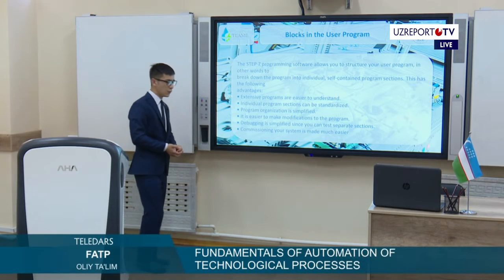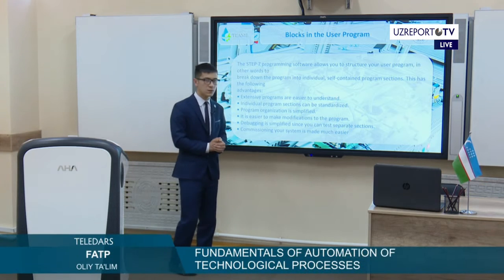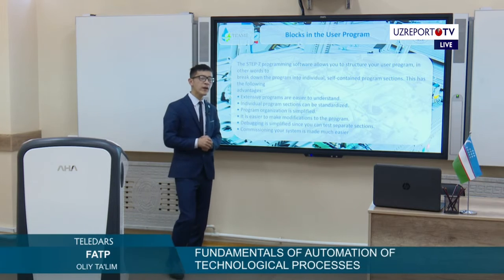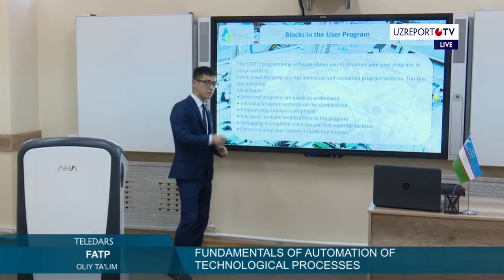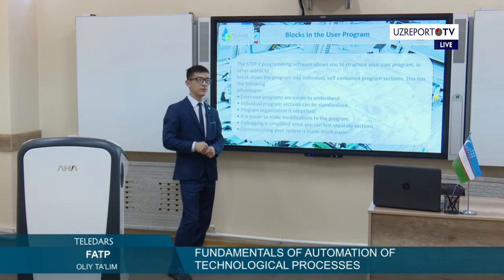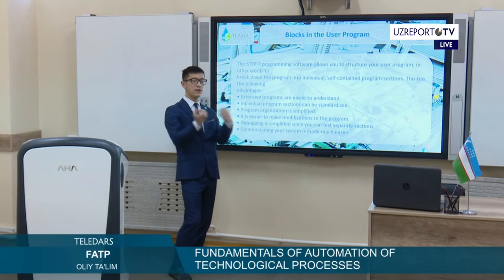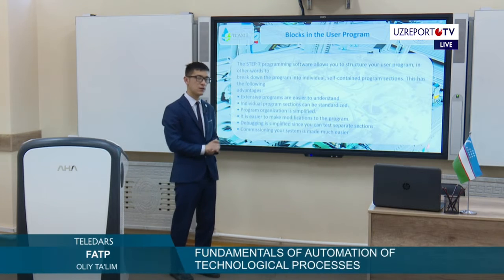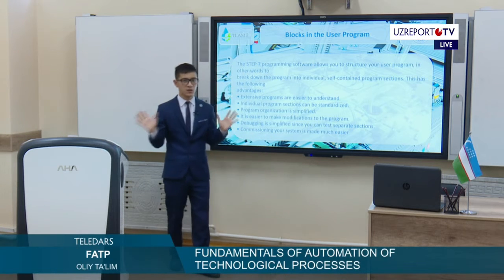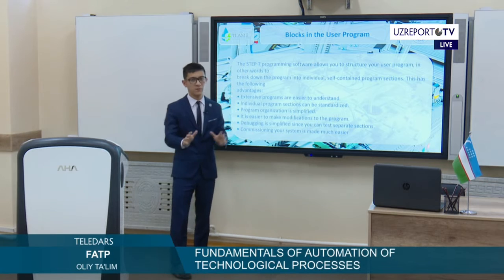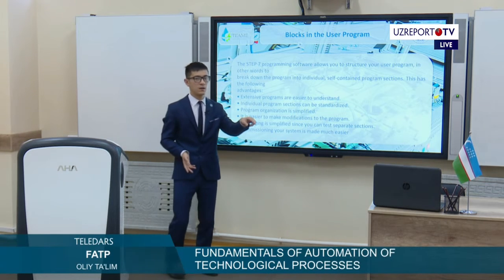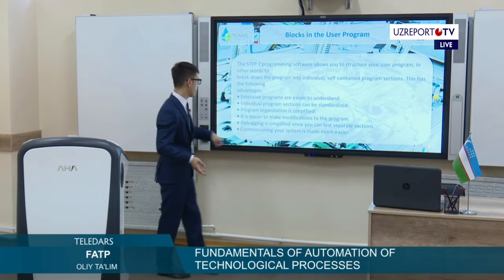Of course, when you download to the controller on the basis of Step 7, if you don't have the same computer to program, you just connect again to the controller and can take out the program, change it, and download again. You don't need any special computer for programming. All computers with Step 7 can take out the program which is in the controller.